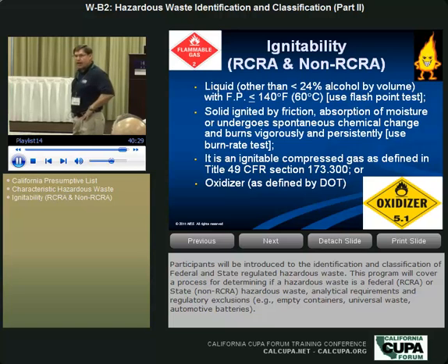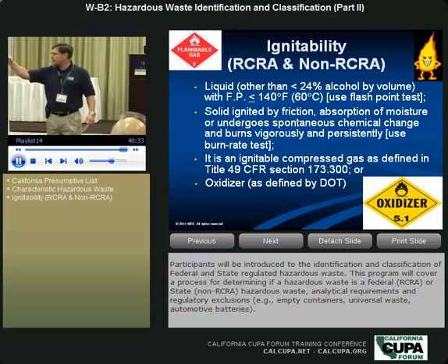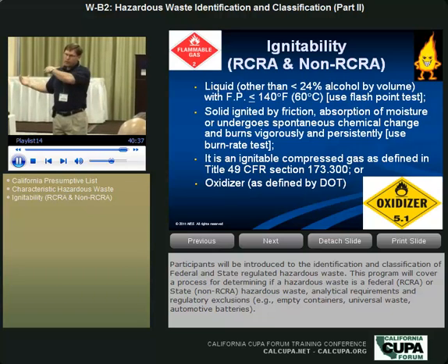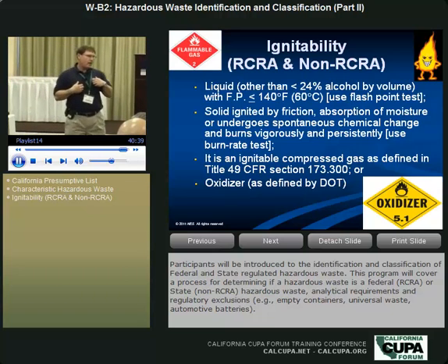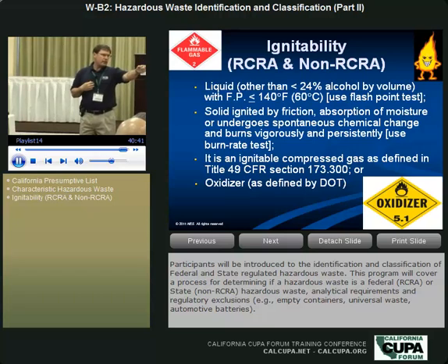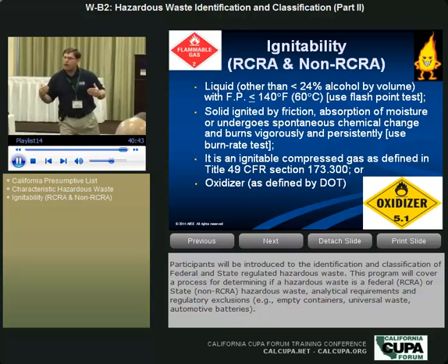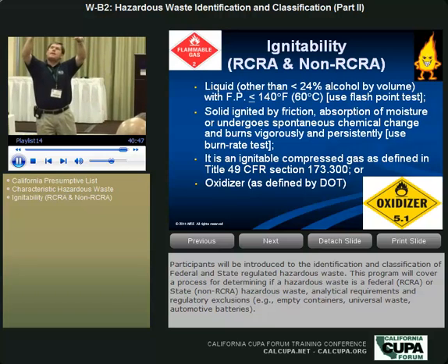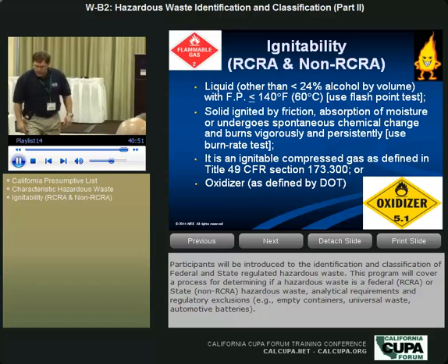Yeah, if it's pretty saturated, but then I better be storing it in an airtight container because of the VOCs. And if I'm a large quantity generator because of CC, it probably needs to be an airtight container because it's in a 55-gallon drum that's not being scrubbed. But I can keep it in a process to recover those vapors if the container's not being scrubbed, where it's a flip-top UL-listed container that doesn't have to be airtight, but it's enclosed.